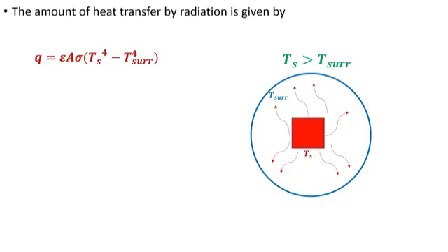If we put the value of temperature in degree centigrade rather than Kelvin, then our result will be full of error. So in order to eliminate those errors, we should put the value of temperature in Kelvin scale. For conduction and convection, we can put the value of temperature in either degree centigrade or Kelvin, but for radiation it is mandatory to put the value in Kelvin scale.